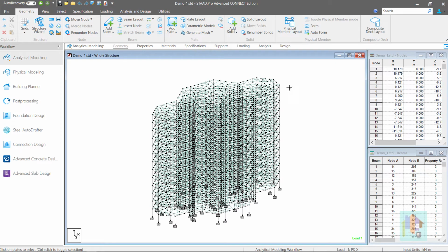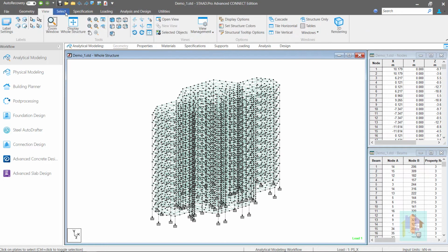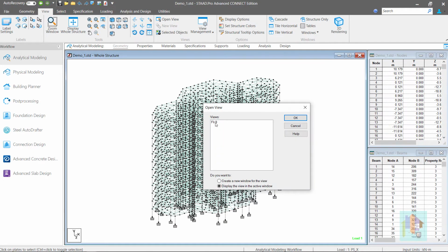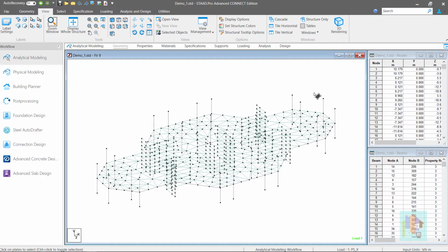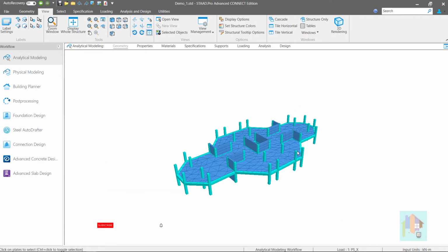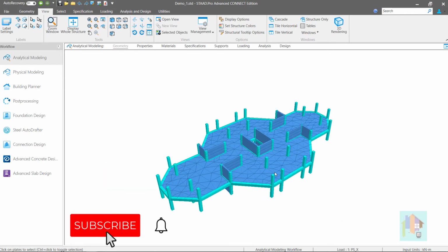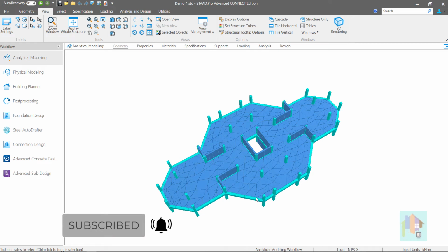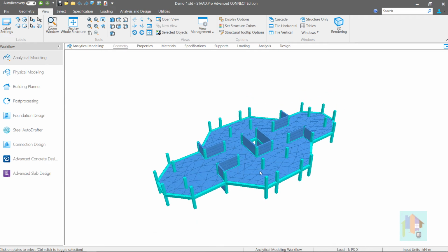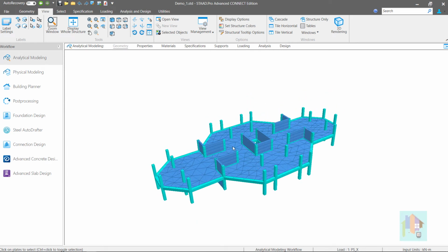Use of finite element mesh in a structural model is very common. If you want to design a floor diaphragm using accurate design strip method or as a post-tension slab, then you need to model it using plate element. Design of concrete slab using plate results is much more accurate than traditional panel method, and for a complex slab geometry with opening, this is the only way.